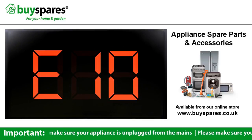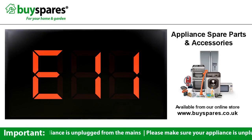E10 error suggests a motorized selector fault on old machines or drum sensor device if fitted. E11 error is open circuit dryer heater / sensor or module. Check the wires to the sensor at the top of the front of the drum. These commonly break from movement on the spin.